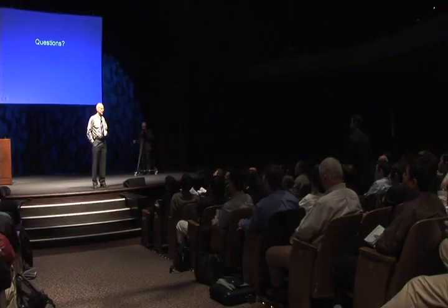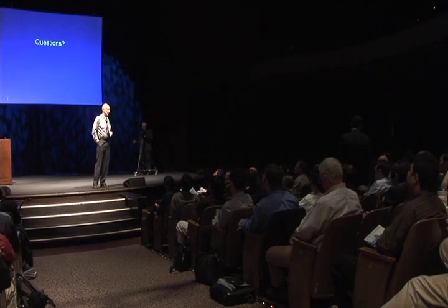Did you say gross deformations or sliding and uplift and things? Yeah, I would like to distinguish that they're not really large displacement effects. You don't have to do a large displacement analysis for this. If it's uplift on a foundation, basically that's kind of a gap type element, and you can do that. If it's pounding between a couple of buildings, again, it's a gap type element. You can do that also.